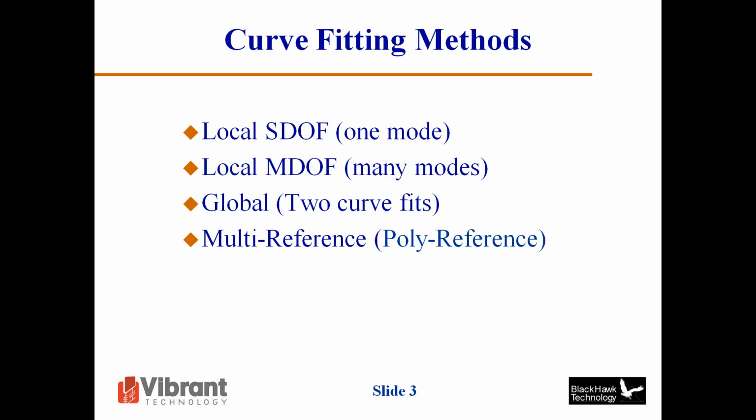In other words, the resonance peaks in our data only show evidence of one mode, but in fact there's two or more modes there. And then a more extreme case called a repeated root, where we have two modes with different mode shapes but exactly the same frequencies. So we'll look at both of those cases.